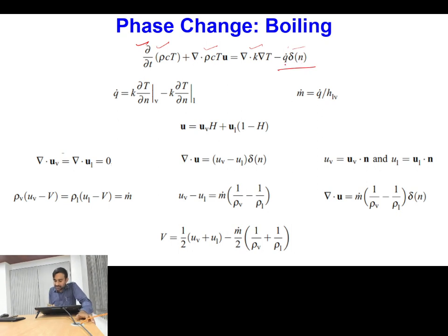And the source term, if you are considering a boiling phenomenon, will mostly be acting at some interfacial boundary, because the interfacial volume will be converting from liquid to vapor. Okay, so we need to estimate this near the interface.